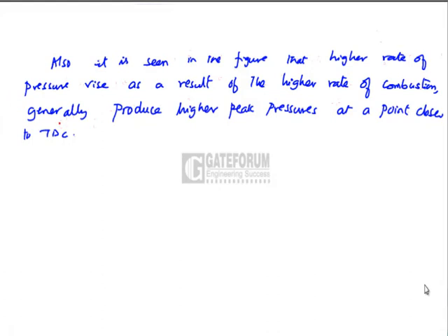In fact, it is generally a desirable feature, because higher peak pressures closer to TDC produce a greater force acting on the piston through a larger part of the power stroke, and hence increase the power output of the engine.